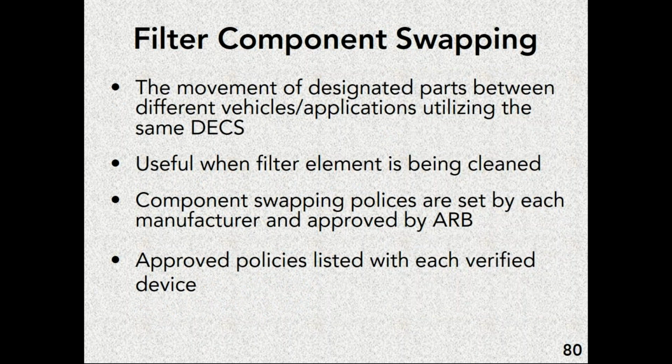I do have to talk about something called component swapping, because this happens with some people, whether you're talking OEM or retrofit filters. When the filter's clogged, you can't use the vehicle until the filter's cleaned out. So some people will keep an extra filter core handy to drop in while they have the other core cleaned out.